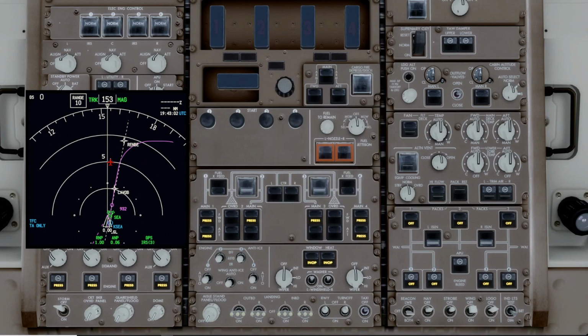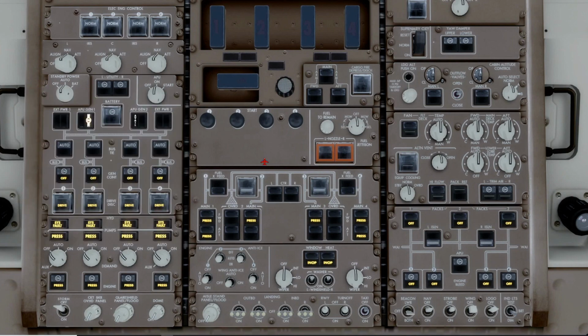Okay, so with that, we'll do the first officer's flight deck preparation. We'll check that the EECs are normal, the alternate lights are extinguished, the IRUs are in nav, standby power is in auto, utility buses are on, the off lights are extinguished, the APU started. We've got APU generator 1. We'll say they're done with loading now, so we'll put on APU generator 2.